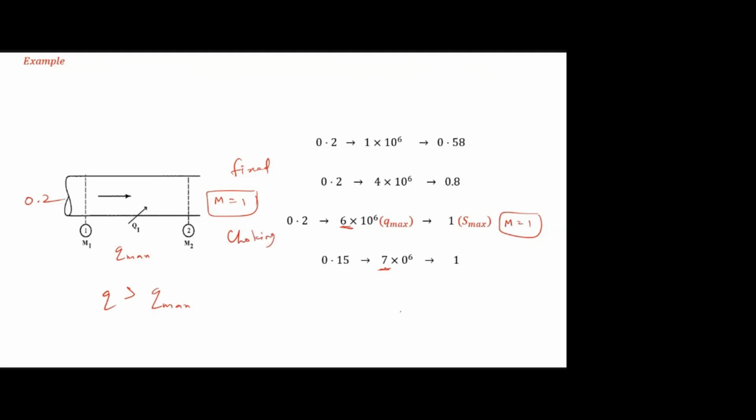So in that time, how will nature adapt? What they have observed is there are propagating pressure waves in the upstream direction, which change the flow region next to the inlet. So due to this pressure propagation upstream, this inlet Mach number is further reduced.